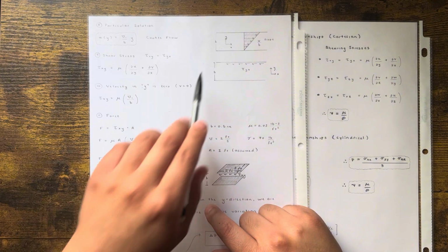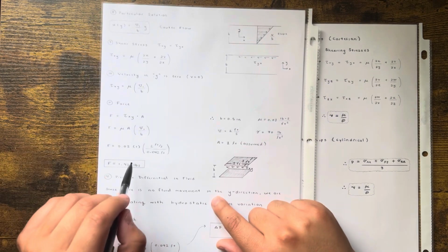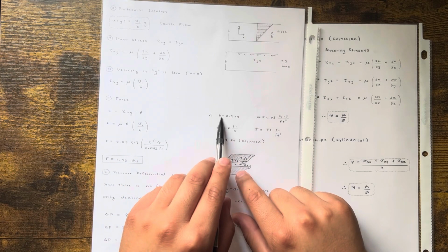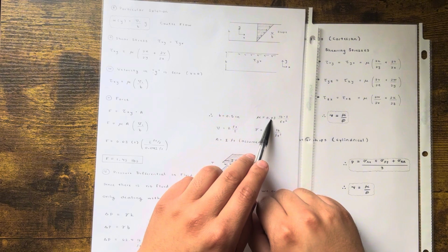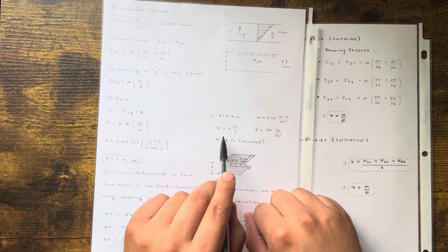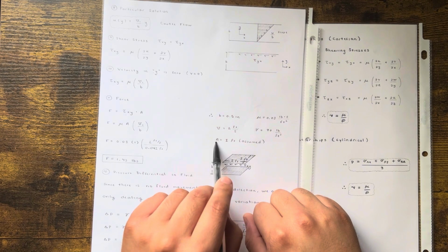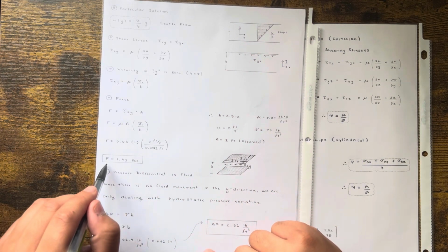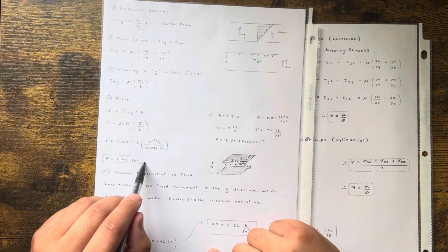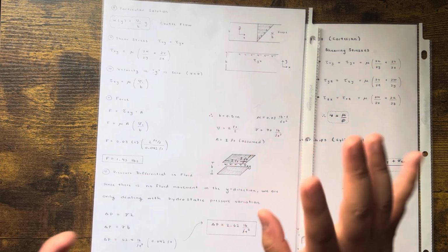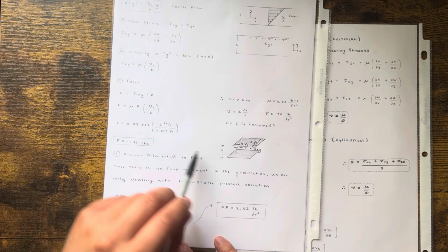B had to get converted. This was 0.5 inches. I had to convert it to feet. So when I plug in all my numbers, B is equal to 0.5 inches or 0.042 feet. Mu is equal to 0.03 pound seconds per feet squared. U is equal to 2 feet per second. Gamma, we don't need it yet, but we'll need it. And then area, right? I found my force. This is per unit length, so this should have been per feet squared. My bad, I forgot to write it down. It's okay, no big deal. But this is per feet squared, okay? Pounds per feet squared.